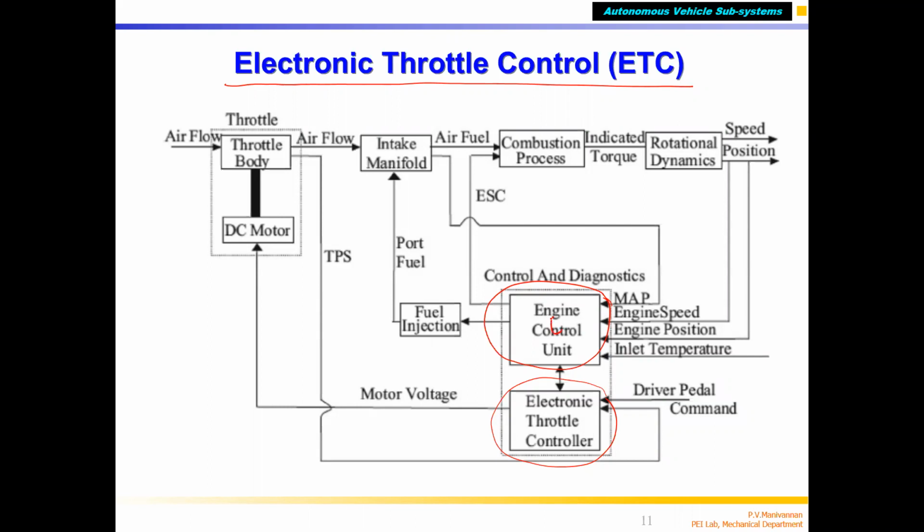So for ECU1 and ECU2, you have to develop both, write the program, store it, connect to the injector, connect to the DC motor, and conduct the experiment. If it does not work, you make corrections, changes in software or hardware, and make the engine work as per your vision, with the required speed omega or theta or torque. This is what the engine outputs.